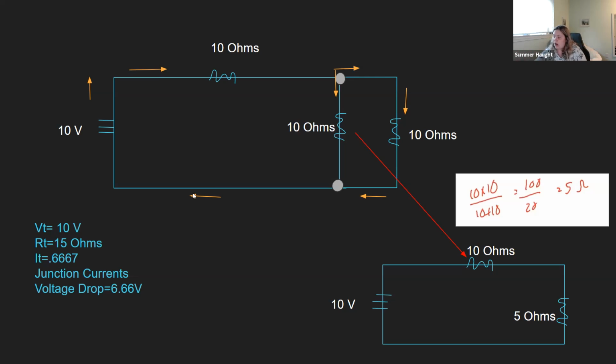So the first thing here is in the videos they talk about situations where you have parallel resistors or parallel circuits. These are the parallel resistors because they're in this parallel situation with these. When you have situations like this where in a combination circuit you have parallel resistors, you should always try to first calculate these together, calculate your total resistance by basically treating this as its own parallel circuit, and then you can add that back up to this series circuit. So I'll explain this in better terms when going over this.